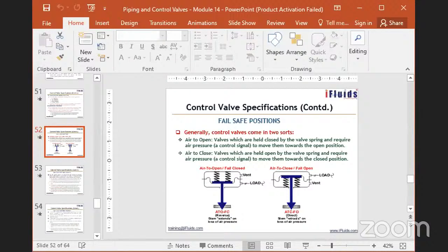Similarly, like a choke valve. When there is a large pressure reduction across a valve, it leads to noise and vibration. So these valves have to be mechanically secured. They should be provided enough mechanical support. The lines, both inlet and outlet, will be anchored to the ground or to the structure nearby. It definitely leads to noise and vibration. If it is needed, it can be measured. The vendor can give you the kind of noise levels it will generate.